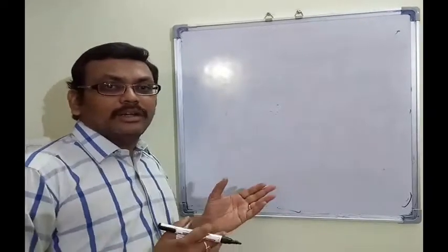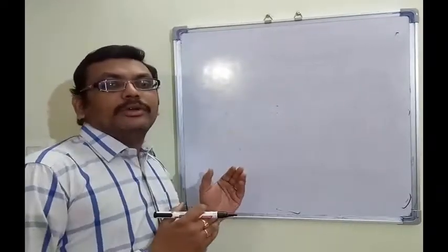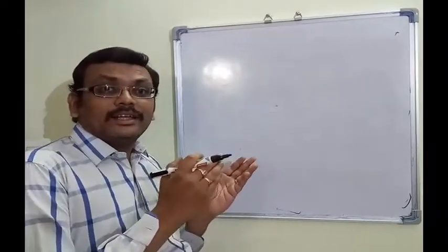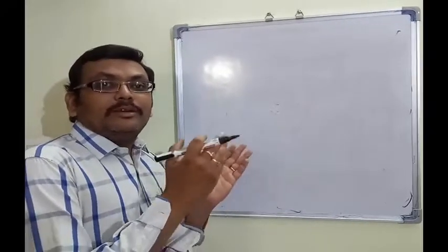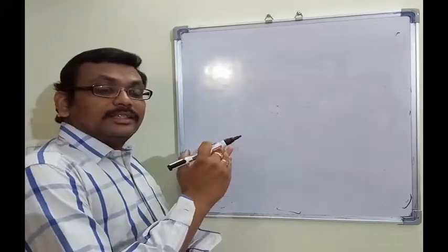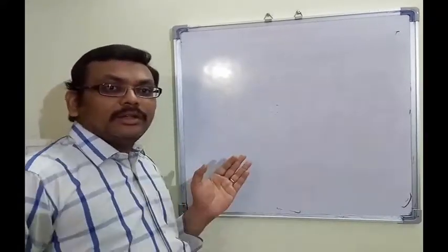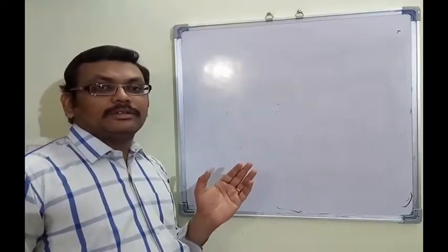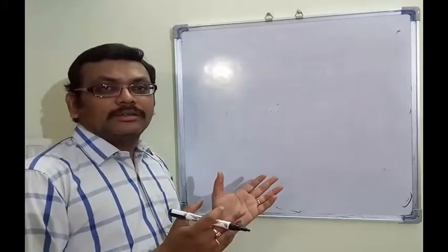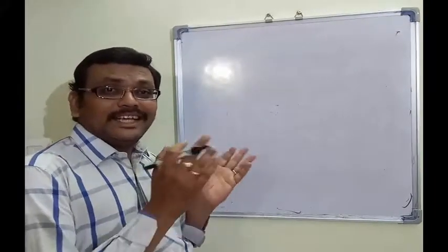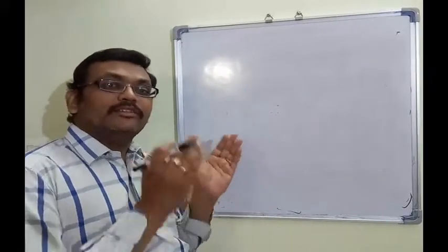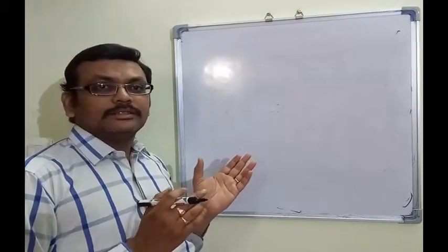exact dimension is not possible without knowing the entire design or what is the purpose of the component and onto which that component is going to mate, and what is the material of the mating component, whether it can mate into the existing component or not, or whether the second component is going to mate into a third component or not. That means we have to know the complete scenario, complete design of the part or design of the component. Then we can decide tolerance.